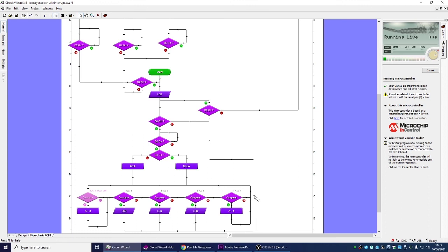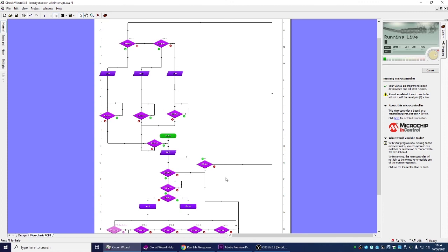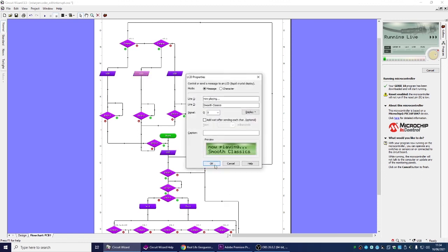Now, when that decision is made, we look at the push button on the rotary encoder. It's a bit of a weird one because this is a push to break switch, or normally closed. You might notice when testing it, if you press it, that you get a 0. So if we get a 0 when it's pressed, we'll come along here and play the radio station. If A is 1, if we've made that decision, when we press the button when the value is 1, then the value will still be 1 up here, and we'll play dance hits. If the value is 2, we'll play smooth classics.